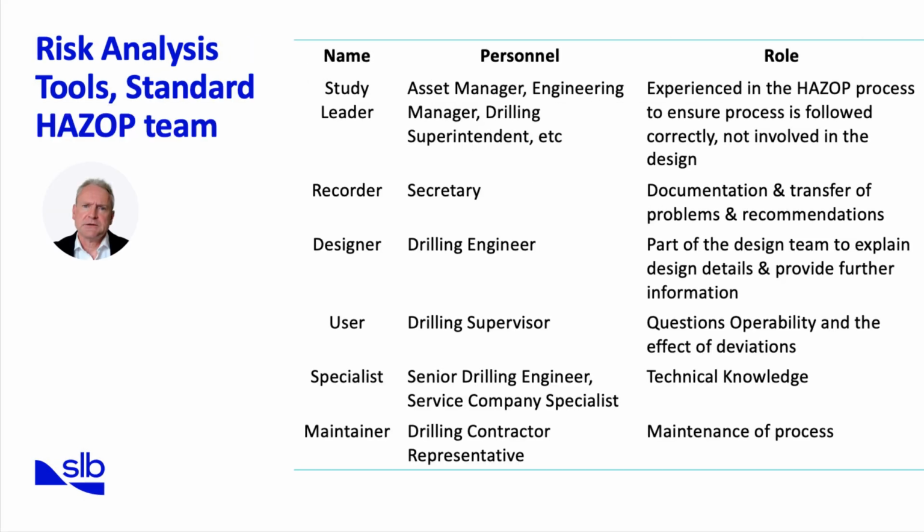For a HAZOP study to be effective, it requires the right team structure, with each member contributing specific expertise. At the top, we have the study leader. This is usually someone like an asset manager, engineering manager, or drilling superintendent. Importantly, the leader is experienced in running HAZOPs but is not part of the design team. Their role is to ensure the process is followed correctly and impartially. Next is the recorder, often a secretary who captures every detail of the discussion, ensuring problems, recommendations, and decisions are properly documented.